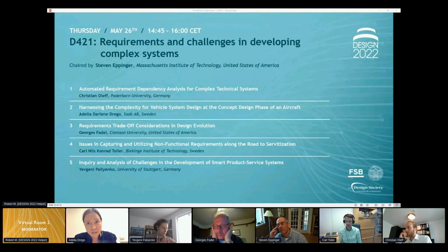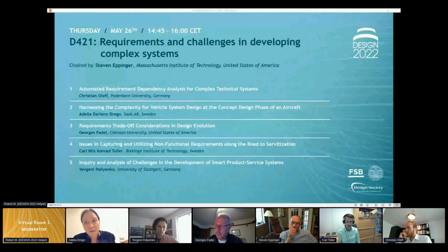Then the next level, at the aircraft level, what modes do we want? As in, how does the aircraft perform a function? Like a mode could be takeoff, a mode could be on ground using auxiliary power. And from that level, looking at each, saying, okay, here's this ECS, what functions at the aircraft level will interact with its functions, and then the same for performance, from physical systems just sitting in its vicinity to its physical interfaces, both its consumers and its providers, and as well its operational envelope.